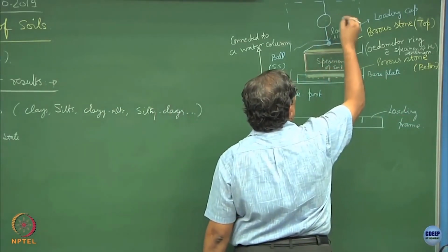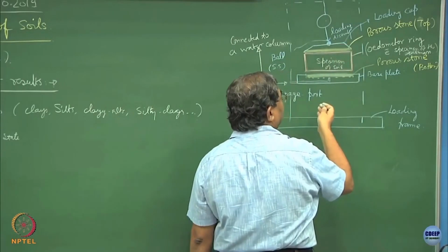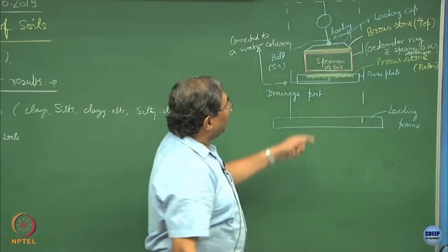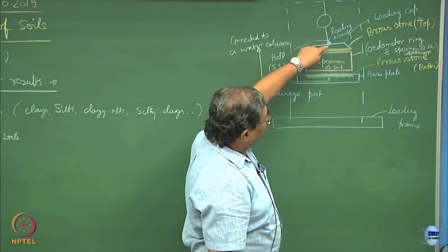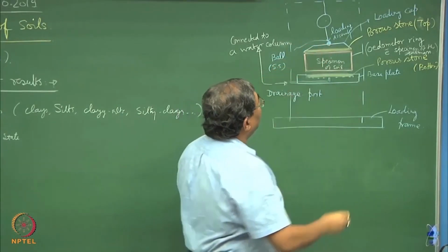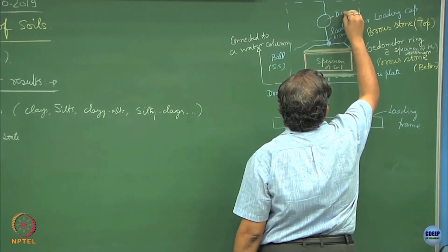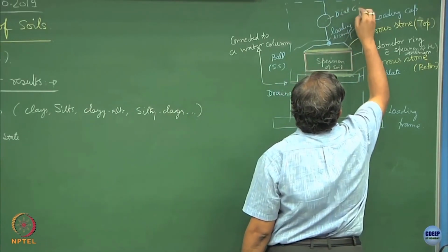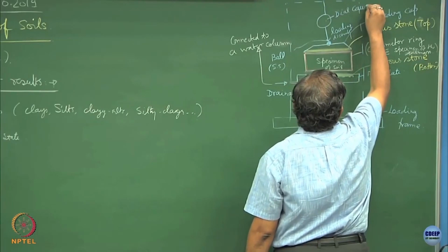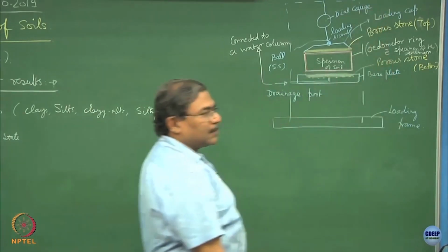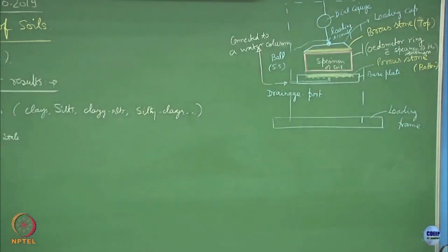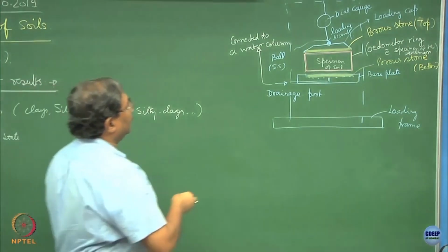I can read how much load I have applied, or I can devise a system by which I can apply a certain known amount of load on the plate. I also attach a dial gauge over here, and this dial gauge gives us the deformation undergone by the specimen when it is loaded.